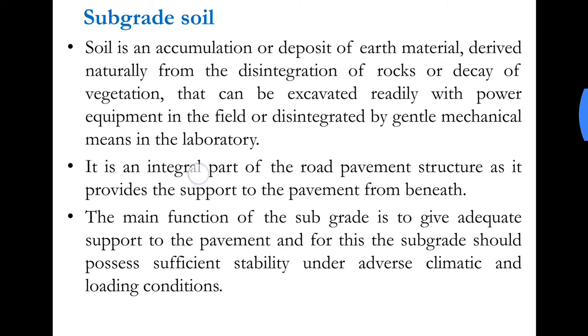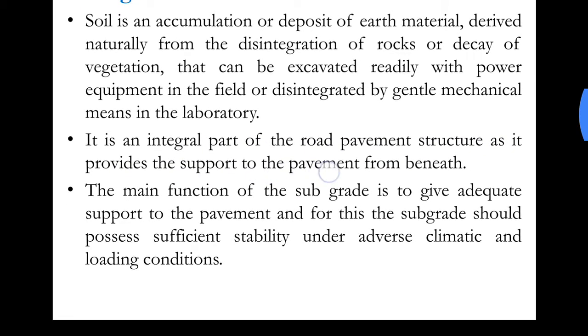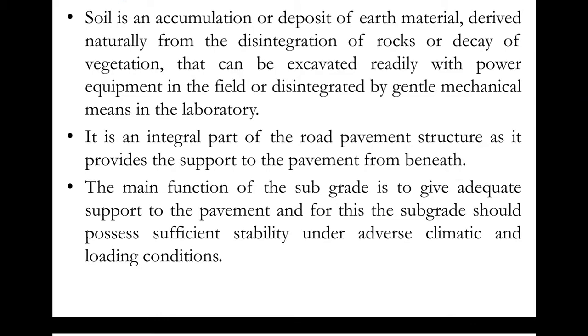It is an integral part of the road pavement structure as it provides the support to the pavement from beneath. So the subgrade is used in order to provide stability or strength to the pavement from beneath, since it is the bottommost layer, and it is the layer which will transfer the load to the earth.